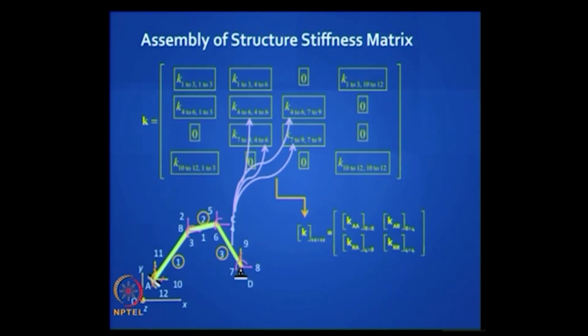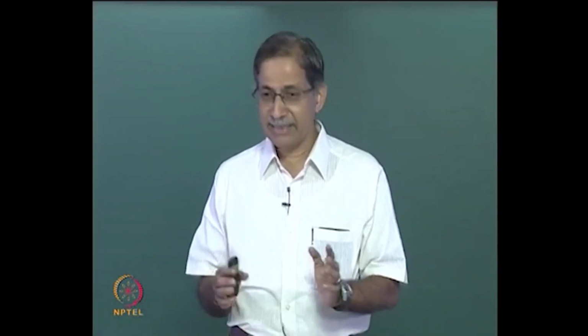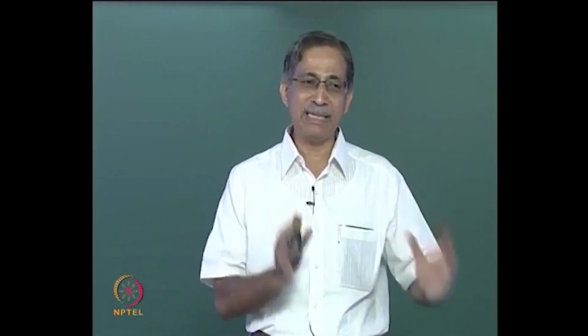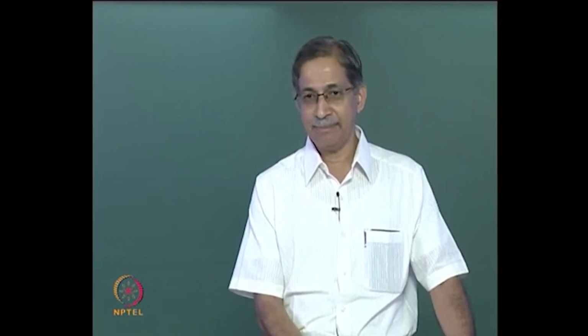Finally, after you have got this matrix, and we will see that there are many other ways of getting the same matrix. There is a reduced element stiffness method, there is another method which we will study soon of getting this matrix, because this has a big advantage that you are playing with little boxes. No matrix is more than 3 by 3, so your storage is very elegant, economical. Only thing, you must program it well so that it goes to the right slot.